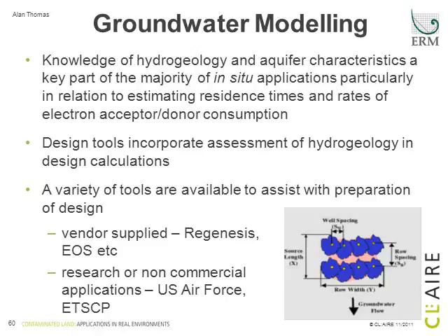But essentially what these tools do is allow you to take into consideration things like contaminant stoichiometry, site hydrogeology and geology, and allow you to develop an outline design that can be used then either to input into a pilot scale trial to allow you to evaluate that, or consider in your full-scale implementation.